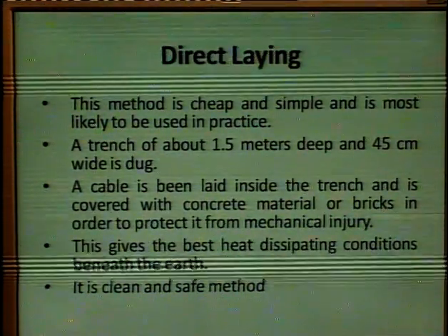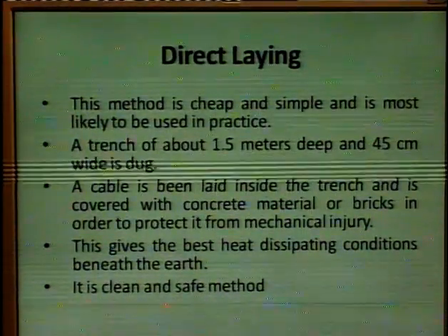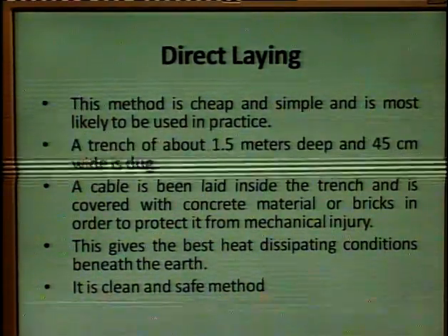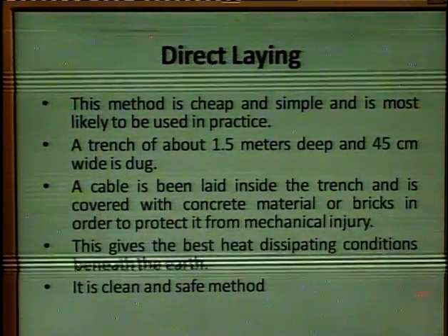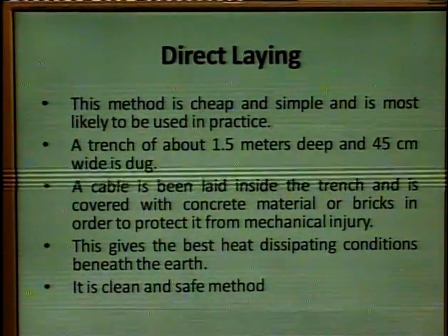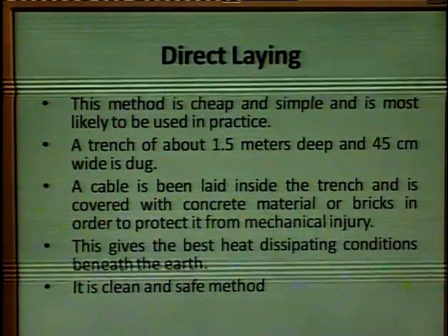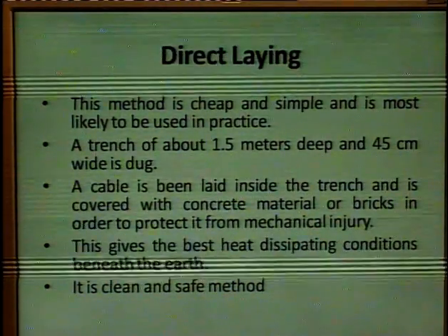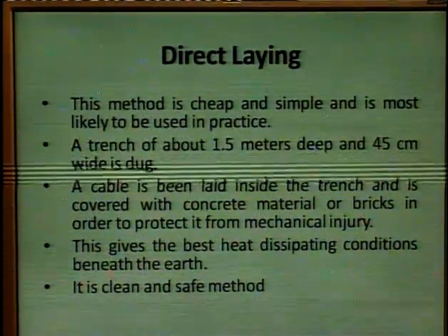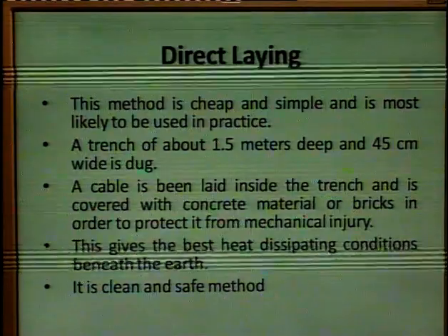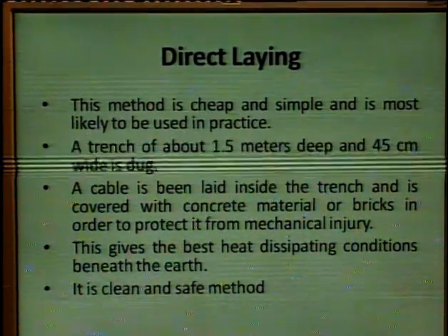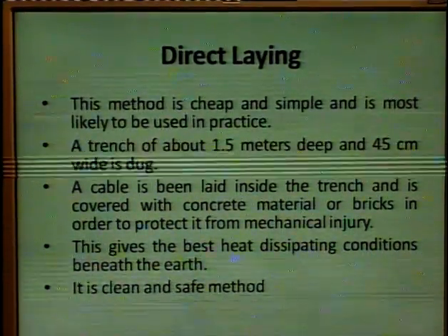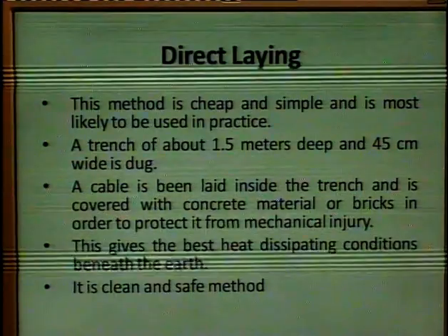Then the cable is laid inside the trench, and it can be covered with concrete or bricks in order to protect it from mechanical injuries. Then it is covered with soil, and it gives better heat dissipating conditions under the earth. And this is a clean and very safe method, direct laying, and it is also a very cheap method. It's the most economical method.